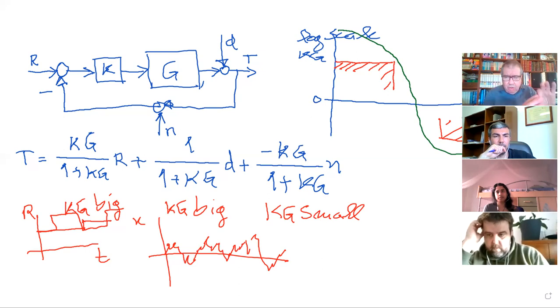No, 0, you don't want it because it's an offset, and it does not correspond to any sound. Now, what you do, you pick up this baseband signal, and then you shift it to a frequency band. This is called a modulator. You have a modulator, and you have to negotiate which frequency band you are going to use.